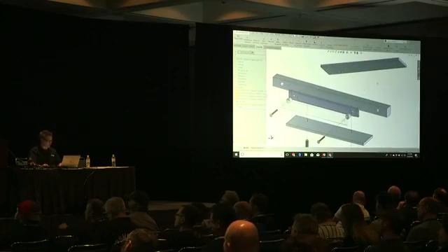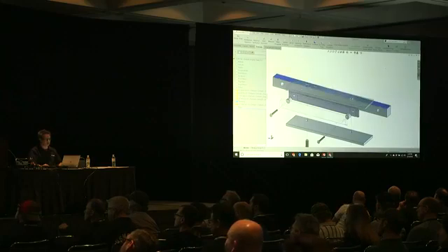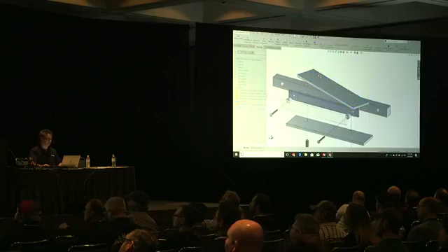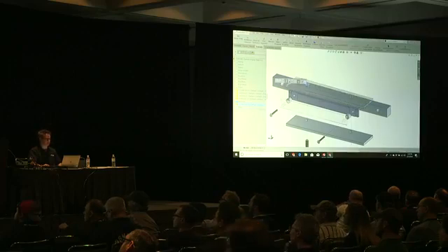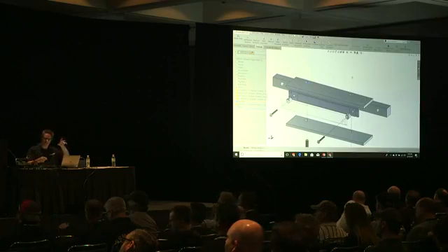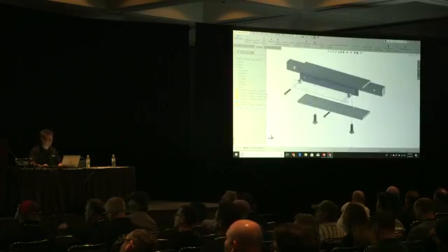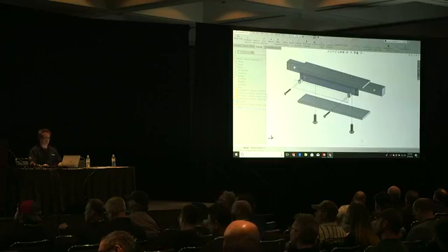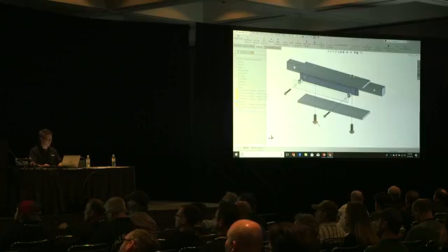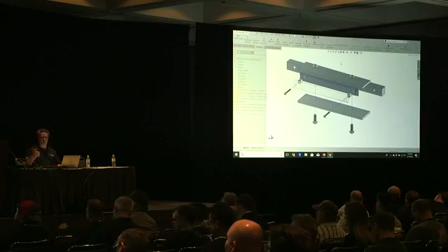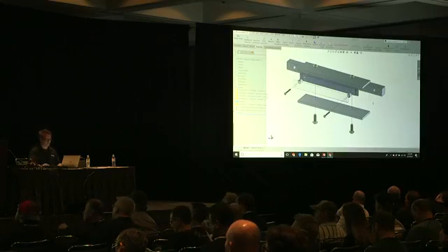Shift, Control, Alt. So if I grab Alt, that's going to activate Smart Mates. So I can do the pin and hole. I want to mate this one, grab that, drag it over here. I've completely mated that part with just modifiers. Alt, Control. Here's a really cool one. I dig this. When you do Control, it copies and drags. When you do Alt, it adds the mate. So Control. Just by doing that, I've copied and added a concentric and added a coincident mate. Cool stuff.